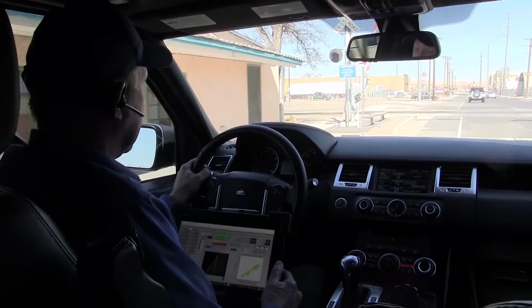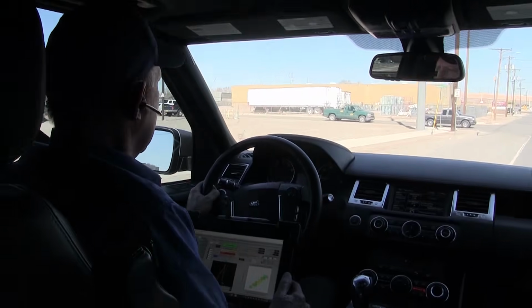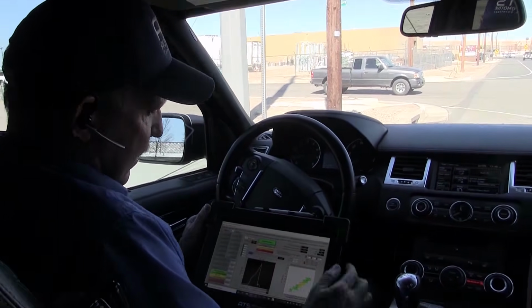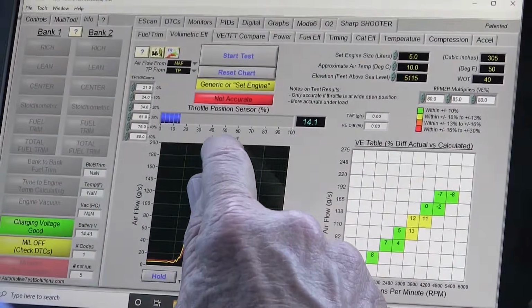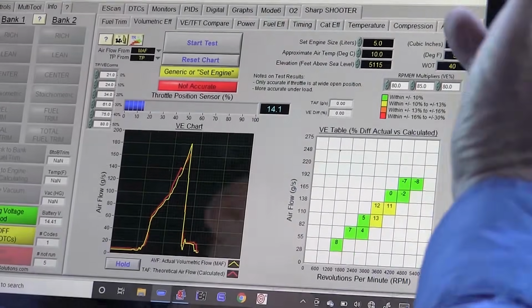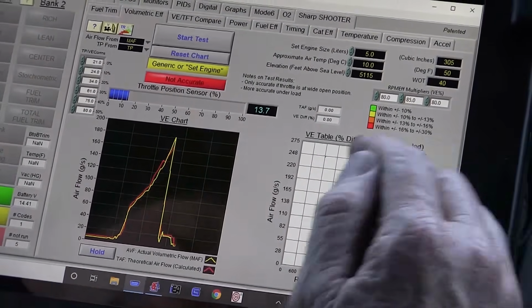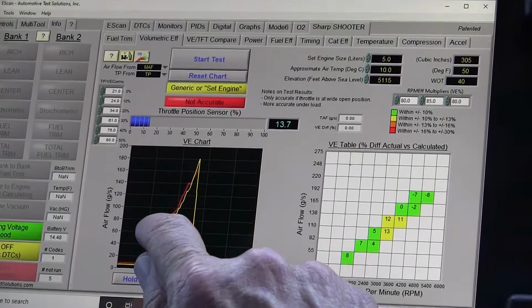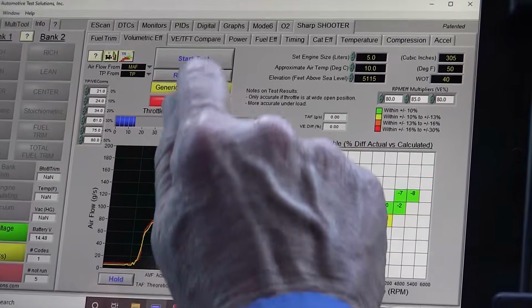We would expect this to do just what it did, and that is the air pulled all the way up, and right there when I got off of it, I felt the engine run really bad. It ran bad, like it was misfiring right there when I came back down to an idle. But this tells me that the air is being read right and we're pumping enough.